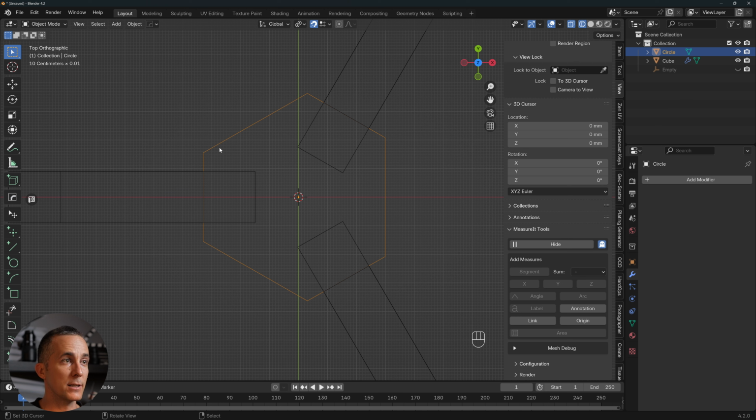Yeah, these curves here. There is a simple way, and that is to use just the Boolean modifiers and get rid of certain parts of the mesh with Boolean modifiers, but that will create a messy mesh, and I don't want that. I want a clean mesh, so I will show you a clean way to do it.